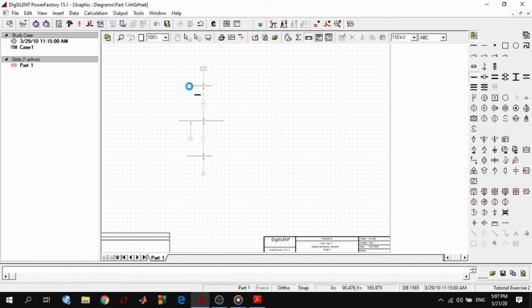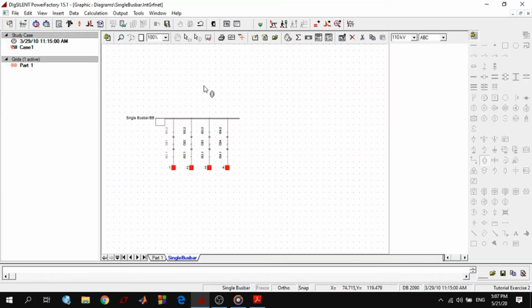By left-clicking on each point of the system, the new busbar is drawn. Then the busbars must be connected with transformers. So left-click on the icon for the two winding transformer in the drawing toolbox. Left-click on the position where you want to put it. Then left-click on the upper terminals and the detailed graphic of this substation is opened automatically.